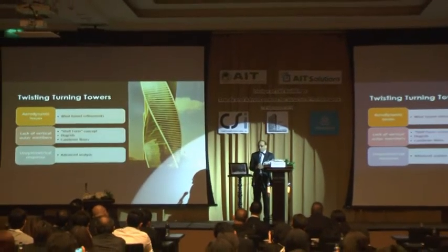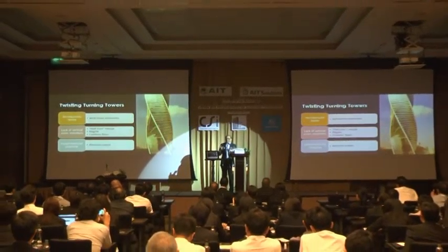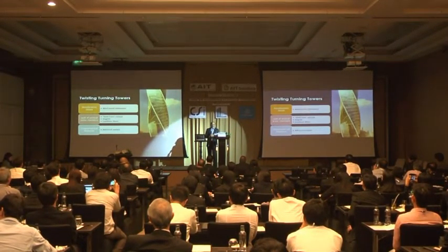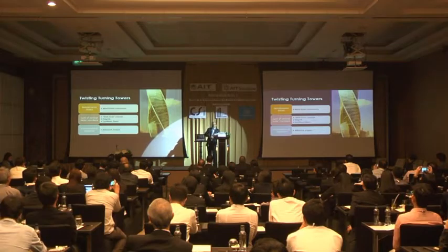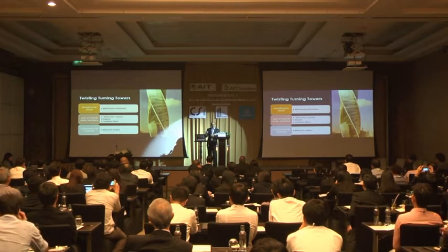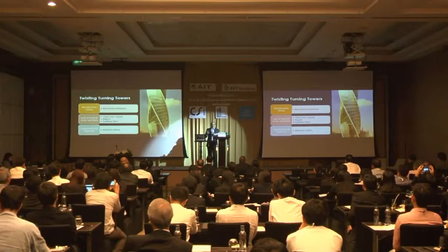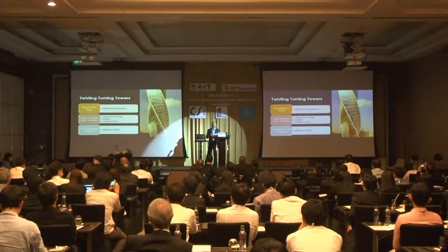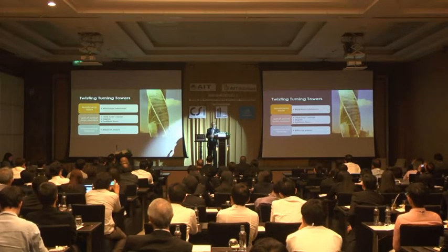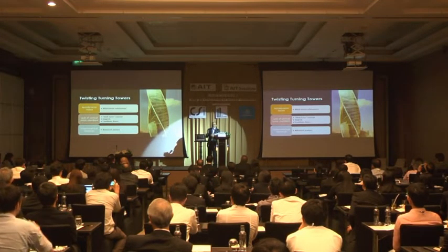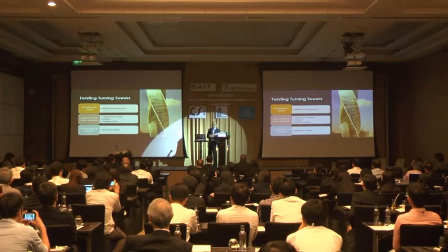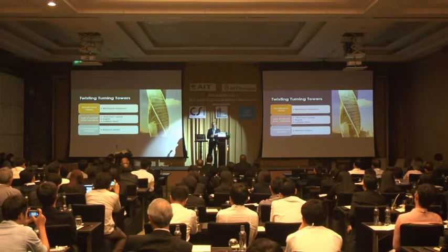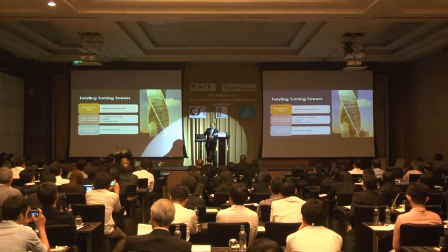And even though we have slabs, we have no concept of vertical columns outside. But actually, if you look at the structure, it's deceptively simple inside. Still the core is vertical, many columns on the edge are still going vertical, cantilever slabs are being done, so they have managed it well without actually making the structure with inclined columns. So deception is very interesting in buildings of this kind. Inside, if you look at the plans, they are able to create these forms without changing the structure much, except some large cantilevers and a few inclined members.